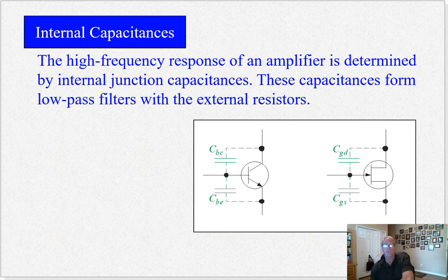Okay, let's talk about high frequency response. That was sort of low frequency response stuff. High frequency response, it turns out that transistors, both BJTs and FETs, what are they? They're three layers. NPN, or drain gate source, whatever, right? But they're like a sandwich. And that sandwich, the bread and the peanut butter and the other piece of bread, they act like capacitor plates, all right? So as you increase the frequency, the capacitance comes into play.